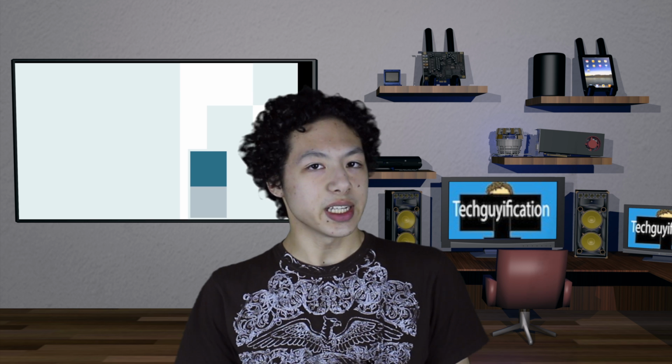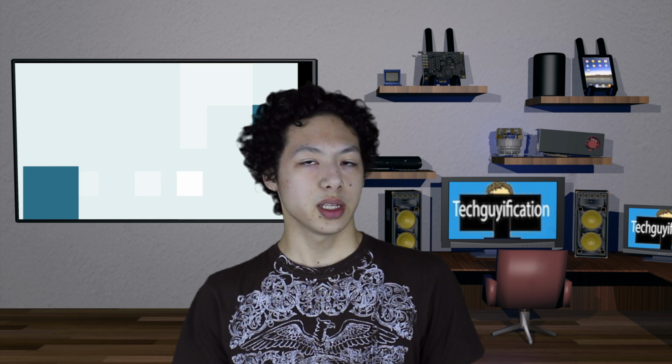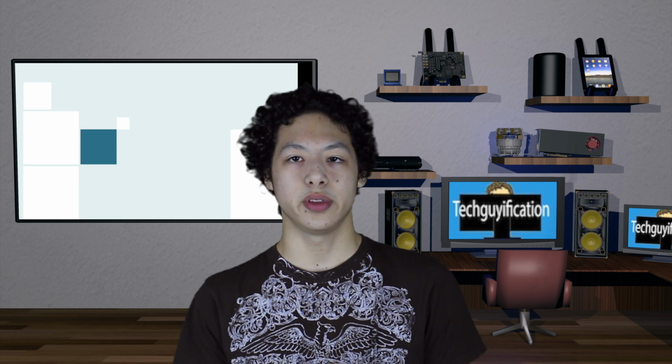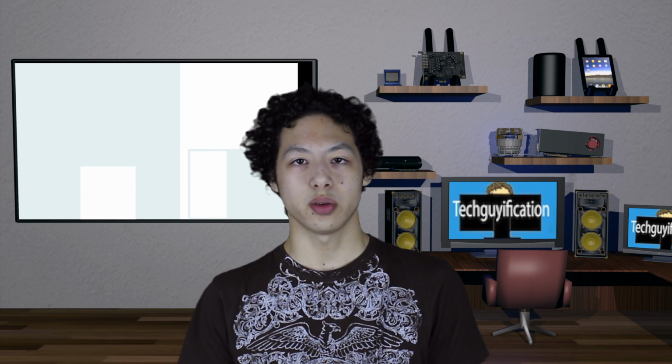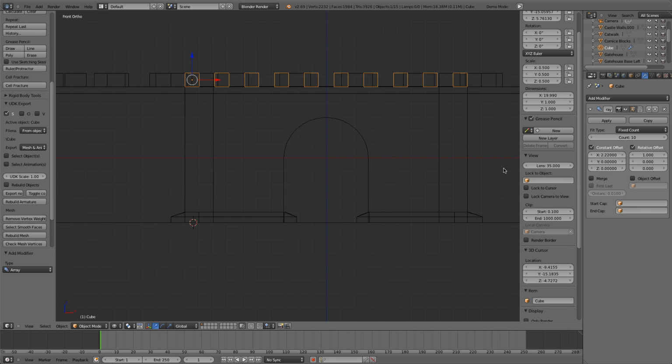Leave everything as is, but check the Constant Offset checkbox and change the X value for that to 2.22. The other thing we're going to change is in the Count section of the Array modifier: change the count number to 10. This creates a number of blocks, but they're still marked as one object. Now name this object Gatehouse Cornice Blocks.